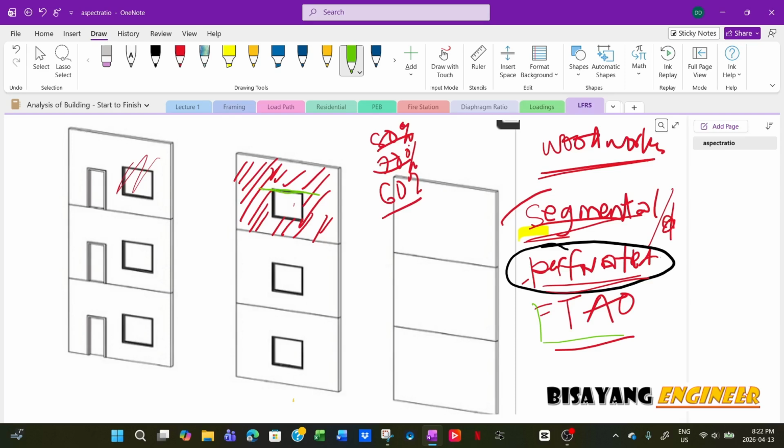So you will see strapping right here, top and bottom of the opening. And the analysis is, I would say, not easy, but not too complicated. It follows the simple mechanics. So if you have the load here, now you can analyze the tension right here, and then compression right here. And if you follow that force, that's the same force going all throughout here, because that's the resultant.